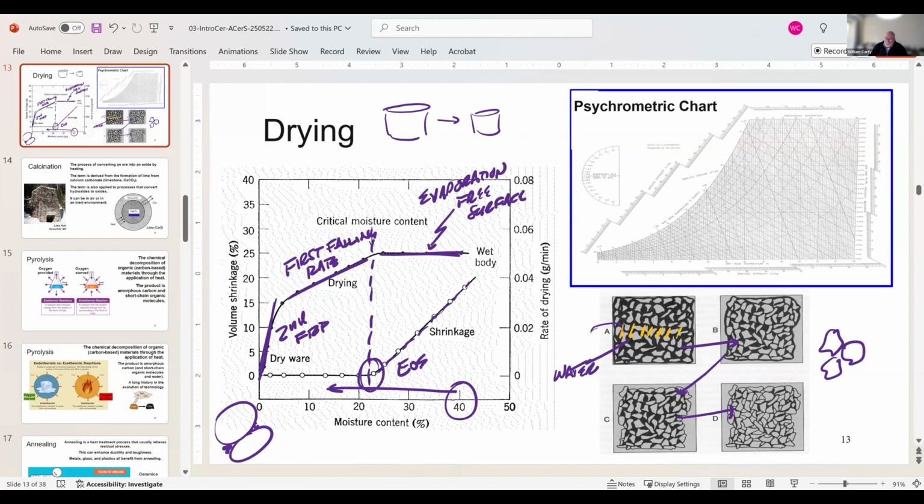And I know this is a coarse particle example, and even with small particles, you do the calculations. To me, there has to be a large amount of particle rearrangement during that drying process where particles actually move. And they probably can't move much more than a diameter, but they will move in relationship to other particles to improve the packing because of capillary forces in the drying process. But the cartoon is reasonable for us, and that's okay.